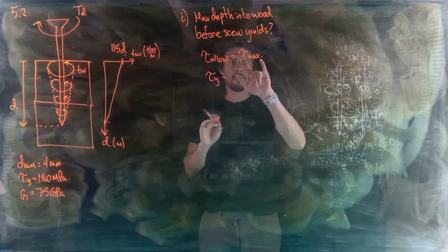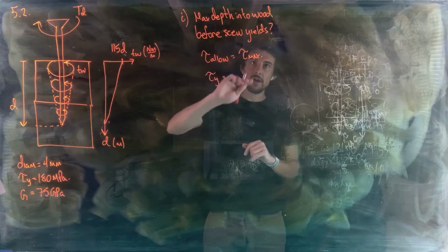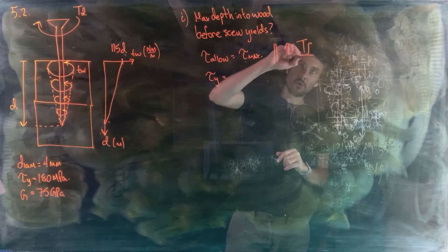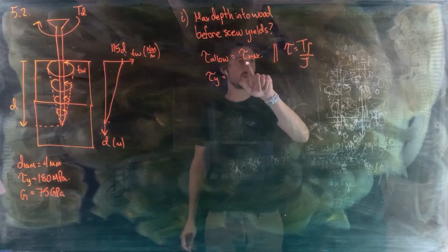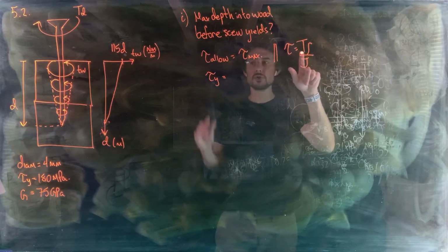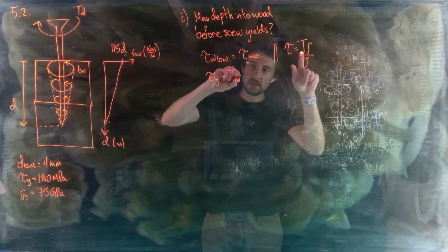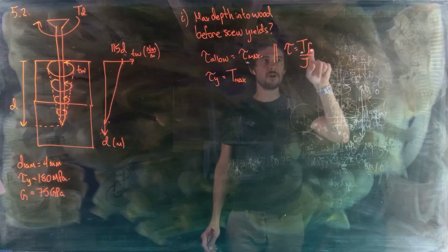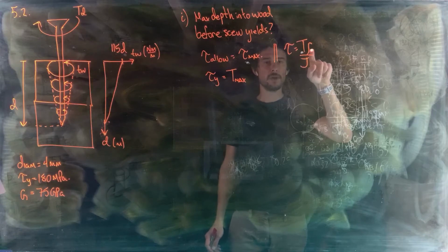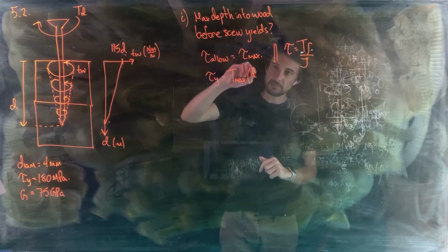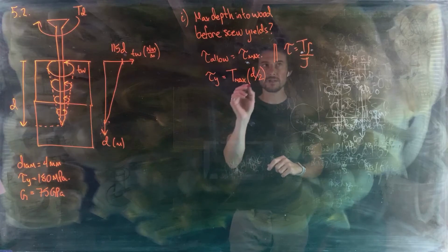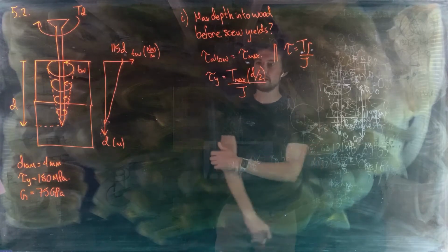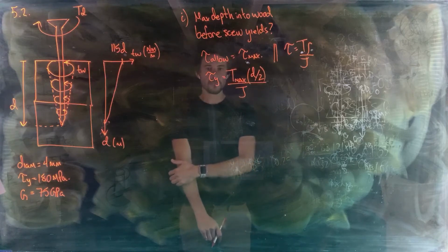And for the maximum shear stress here, again, we're using the equation tau equals T rho over J. But if we want maximum shear stress, the internal torque that we use should be the maximum internal torque that the screw experiences. Variable rho, we want to maximize that, so that becomes the diameter divided by 2, or the radius. And J, we know what J is, a cross-sectional property.